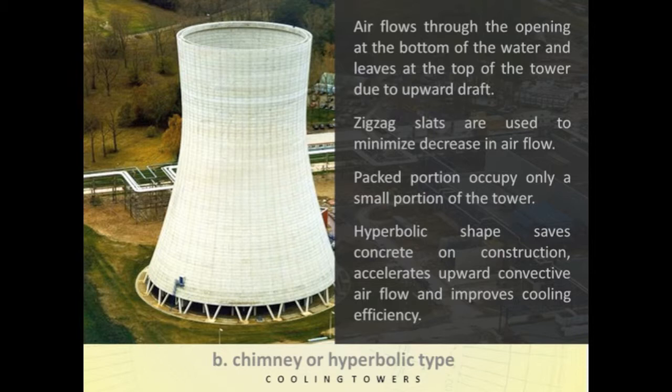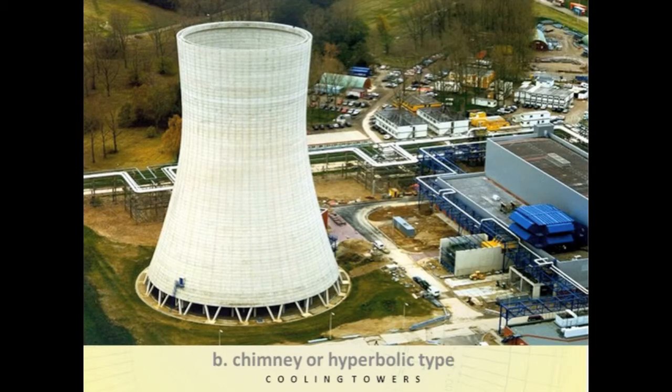Zigzag slats are used to minimize decrease in airflow. The packed portion occupies only a small part of the tower, and the hyperbolic shape saves concrete and construction, accelerates upward convective airflow, and improves cooling efficiency. Here is a picture of an actual hyperbolic type cooling tower.